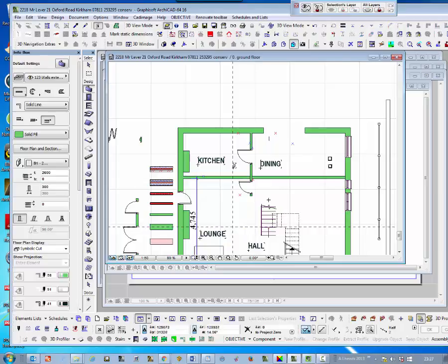Okay. So this one, highlighted it, and as I say, I've got the wall tool selected there. So if we do control, see what it's done there? It's actually split it, because the wall was passing through that wall. Instead of taking it to it, it splits it at the point, which means that we can actually move that bit of wall away and use it later if we need to.